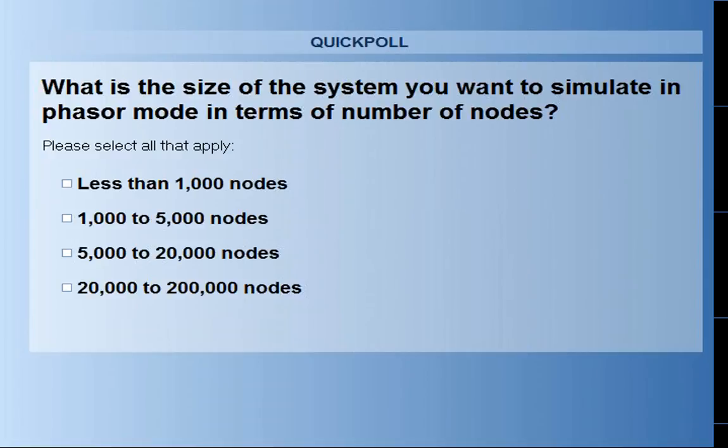On the right-hand side, you are seeing the monitors that I placed there, so we can monitor some parameters. I have chosen to monitor, for example, the rotor angle of the synchronous machine, the frequency of the system, and the voltage of each bus, as you can also see in the figure with the red lines. Also, you can see the current flow on the transmission line with the green line. You can have access to very internal parameters of the simulation, like the excitation reference voltage or the mechanical input of the synchronous machine.